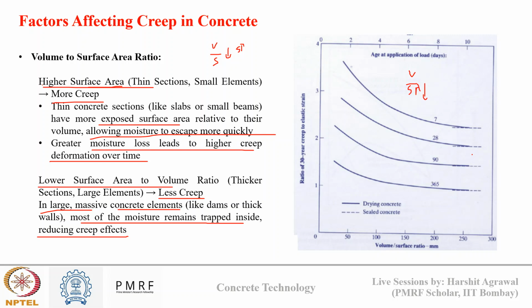Also, with the age of concrete at which the load is applied, we can see that as the age of concrete increases, the ratio of creep also decreases. So this is the effect of the dimension of my concrete.